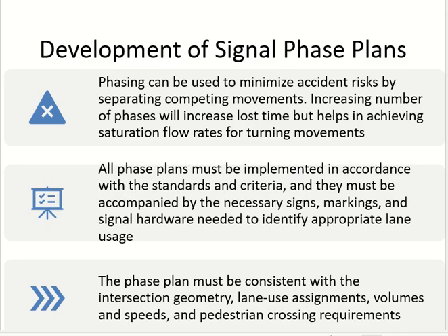So usually we keep the heavier movements together. If it is possible, if they are not conflicting, then you can keep them together, and the light movements together in one phase. That is more productive. If it is not possible, then each heavy movement may have its own phase without combining with any other movement.